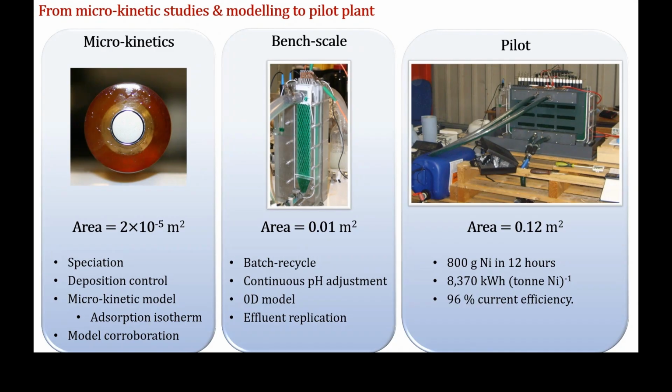Right, so that definitely did happen. So I guess they do that from experience, because from what I understood, this process involved a lot of trial and error. So for example, when we asked them, why do you use pH 2 when it accelerates the degradation of your plating bath, they said, yes, good point. And subsequently they switched to pH 4.